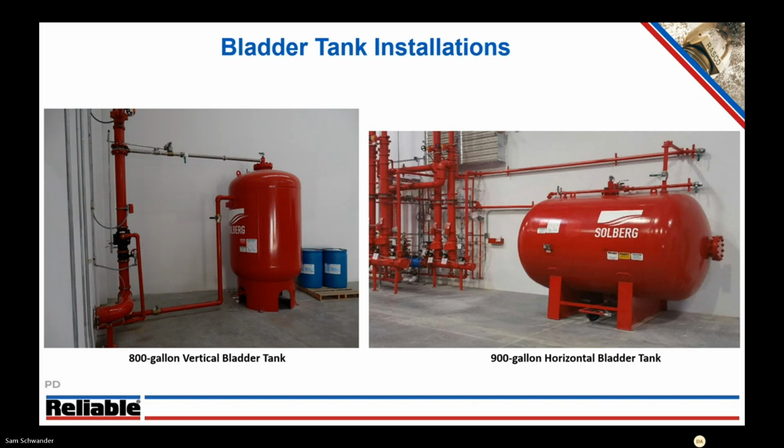Now, as far as materials compatibility, you can see on the left here, the concentrate line is stainless steel. We recommend brass, bronze, stainless steel for the concentrate piping. Keep that in mind as well, which is pretty consistent with what we've been recommending for AFFF systems as well. Also, we can supply multiple different systems with multiple different risers with one bladder tank.